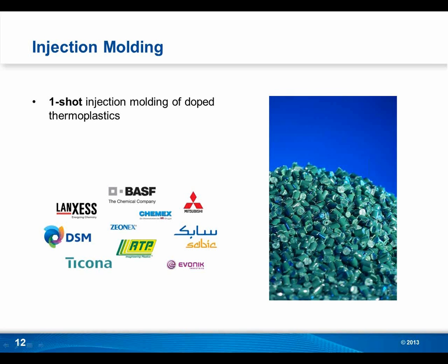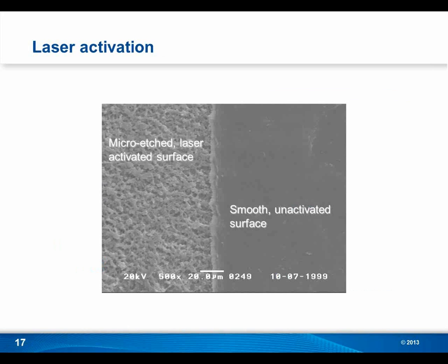Yeah, so the surface has a certain roughness to it, and again, we need this in order to get a reasonable peel strength to the material. So it's an inherent process that we really have to create here. That's not perfectly flat because a cosmetic plating like you see with some consumer devices looks all nice and shiny, but it peels off really quickly. So this is something that we really don't want to do in this application. In order to get an even nicer surface, we probably would have to add another layer of plating to this that really smooths out the surface, and there are some plating applications that can do that for you.